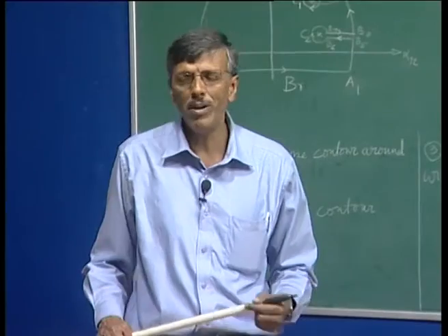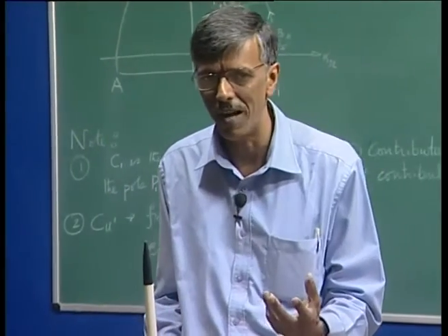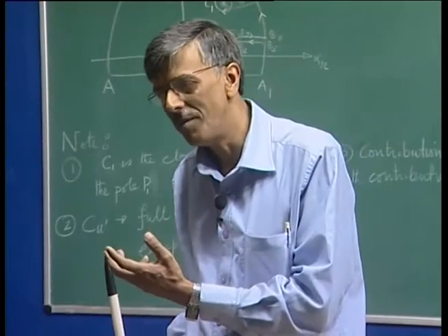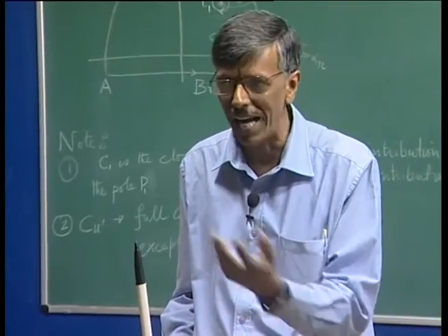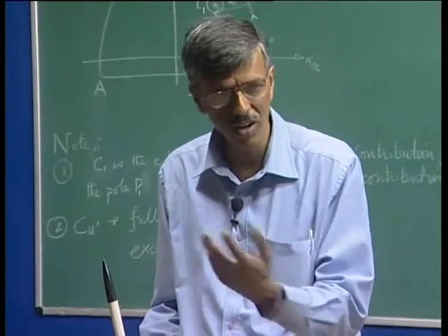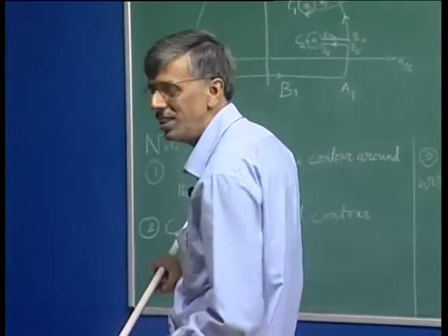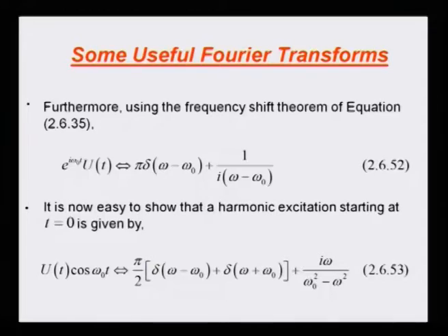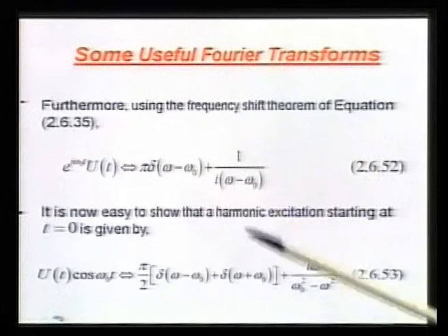Why are we doing this? Because in the physical experiment we have started at a finite time, and when we apply the governing equations, which we will be doing in terms of the Orr-Sommerfeld equation written in the alpha or omega plane, we need to derive those boundary conditions that we are talking about in the spectral plane, and that is what we have established here.